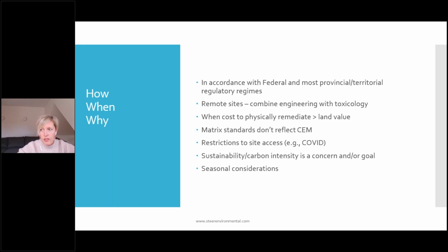So for example, in BC, drinking water standards apply across the site unless you can demonstrate that from a hydrogeological perspective, a viable groundwater well could not be installed. If you can go into the risk assessment and determine it's a remote site, it's probably never going to be developed, nobody's there, we're safe to conclude that the drinking water exposure pathway is inoperable. And then you can apply less stringent standards to the site and risk assess it that way.